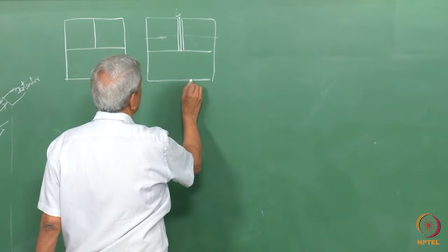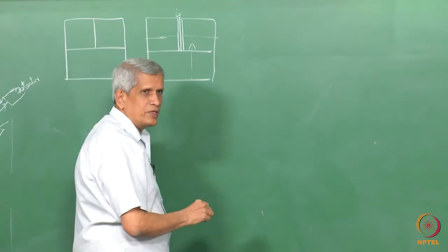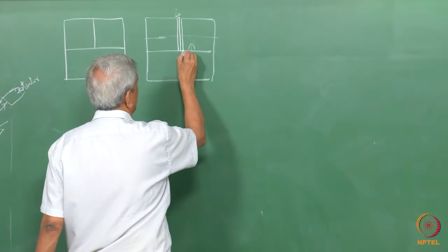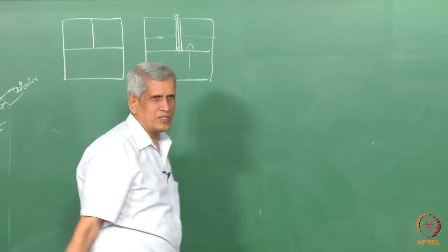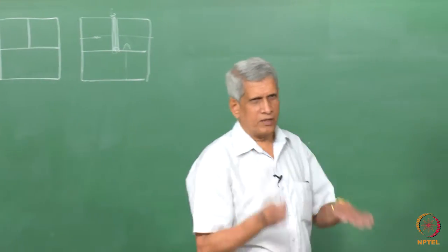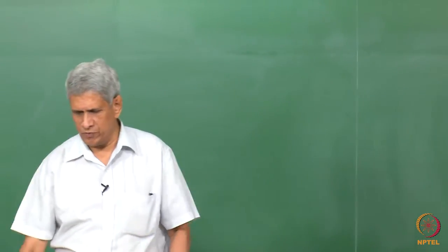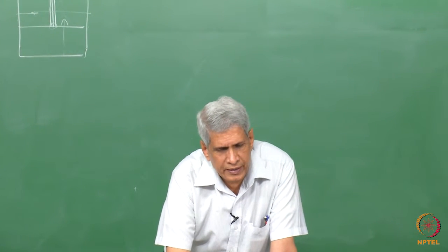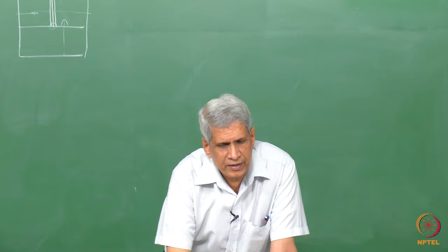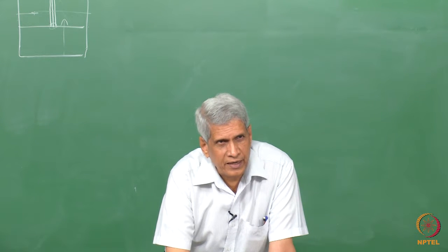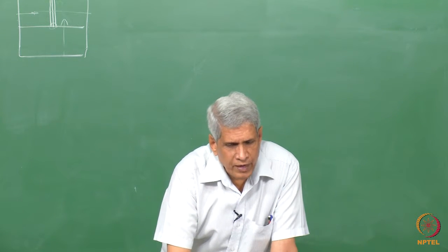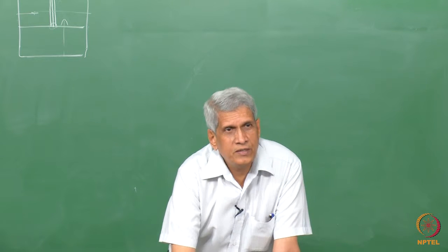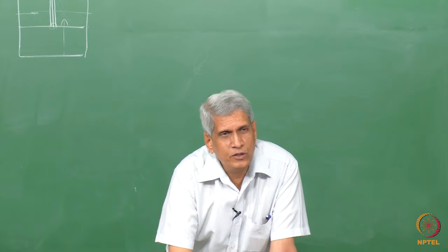But if we go from here to here, what do we see? At this particular point, there is an extra layer coming in. So the one which separates these two layers, where the extra plane is ending, this defect goes like a line from one end of the sample to the other end. This is called the edge dislocation.